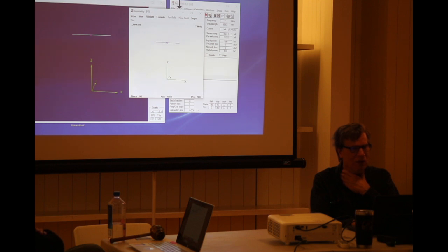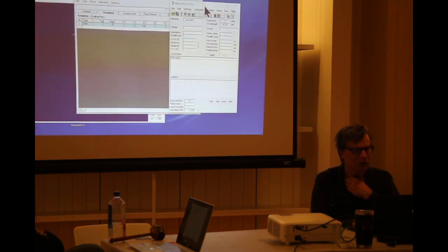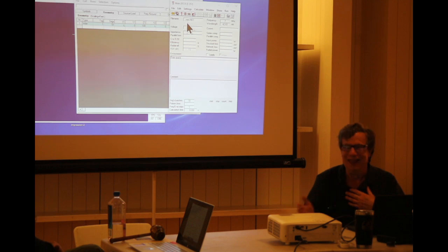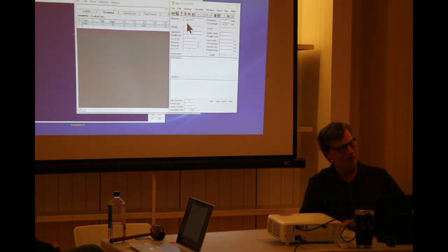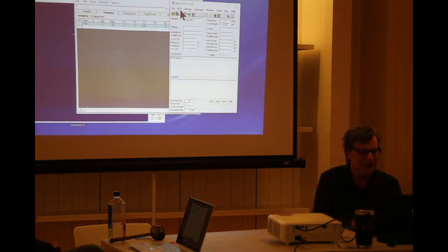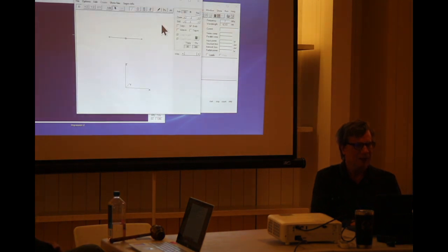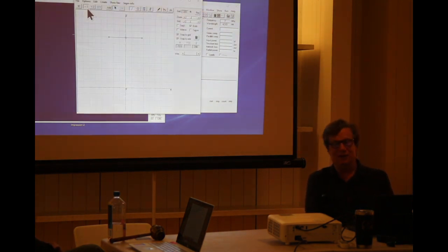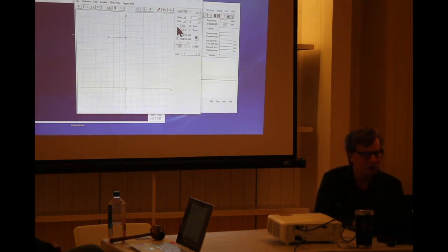Now, how many know that it's impossible to feed a wire exactly at the end? You need another terminal. Otherwise, you're the sound of one hand clapping, okay? If you don't have another terminal, you have a car battery and you don't have a ground end, okay? So you must have something at the other end of an antenna. Now, what we can do here is we'll look at our segments here, and we have a whole bunch of them, and the more segments, generally the better, except you can make it harder to calculate.